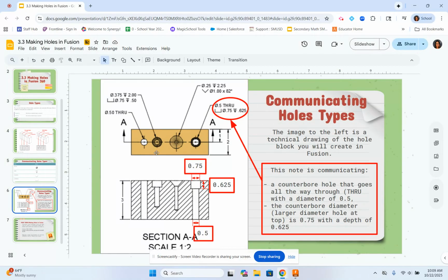So here's our drawing. We need to create this block, and then we're going to add these few holes in here. We're going to utilize these dimensions and also these dimensions up here, okay? The first thing, we're going to create a block that is 2 inches by 3 inches. And then going across, that's a 1/4 of an inch, another 1/4. We're going to make it about 6 inches going across. I realize that dimension's not on there, but we're going to assume it's 6, okay?